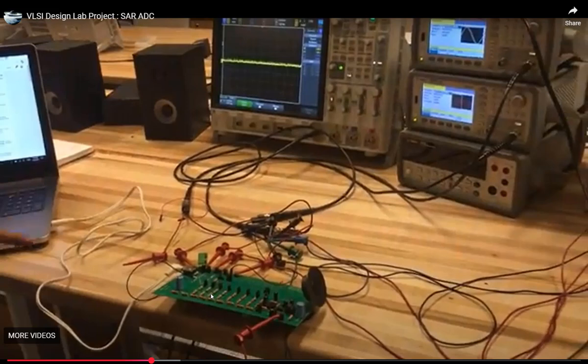So what they did is, you can see all these resistor strings. Is that familiar to you guys? What is that? It's an R2R DAC. So the ADC they designed has an 8-bit digital output, and eventually these 8 bits are connected to, for example, these lines, right? So these are connected to all these R2R DAC, and eventually it's converted to an analog signal to the output on the PCB. So they got a chip, got an R2R string, and analog output here.